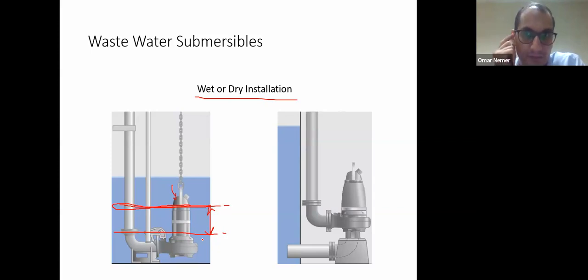Okay? If it's 1 minute, for example, it's okay. You don't need a cooling jacket. But if you need a longer time to empty, then you need a cooling jacket. Otherwise, keep the pump submerged, the motor submerged.